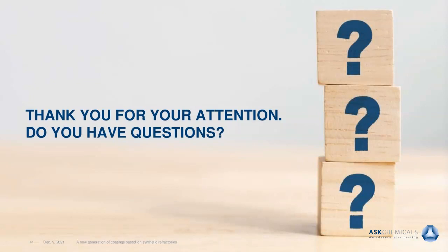Yeah, totally right. I would like to add an experience from the field. Maybe not everybody is aware that a magnesite-based coating applied on the mold and dried will suck humidity over time. It means when these foundries store their cores or molds a few days and there is humidity in the air, this dried coating will take the humidity out of the air and may lead to gas defects later on. Good point.